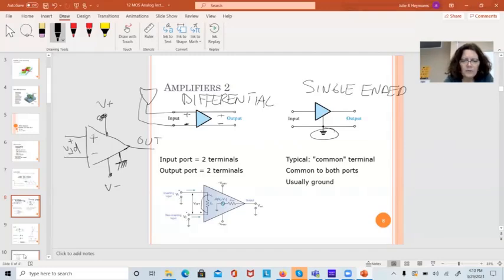They have input resistance. They have output resistance. The output resistance limits the amount of current you can drive from them and how small of a load resistor you can put here. Your load resistance has to be bigger than Z out. So it's good to know what Z out, or R out, is. And this resistance right here leads to a non-ideal voltage across these two terminals.